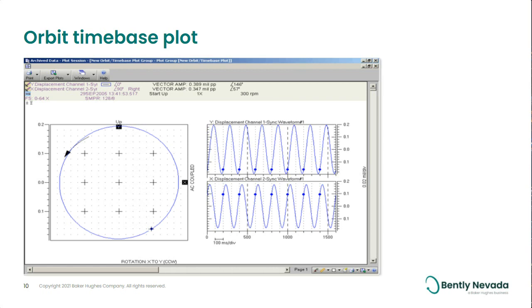away from your shoulder. So in this case, it isn't unbalance because I look at the speed and I see that it's 300 RPM. So 300 RPM is probably not going to be an unbalance. The other thing is I look at the amplitudes and they're in the 0.4 mil range. So this plot has been auto-scaled, and it probably ought to be manually scaled, okay? But this is the type of information that we want to look at when we're doing rotordynamic diagnostics.